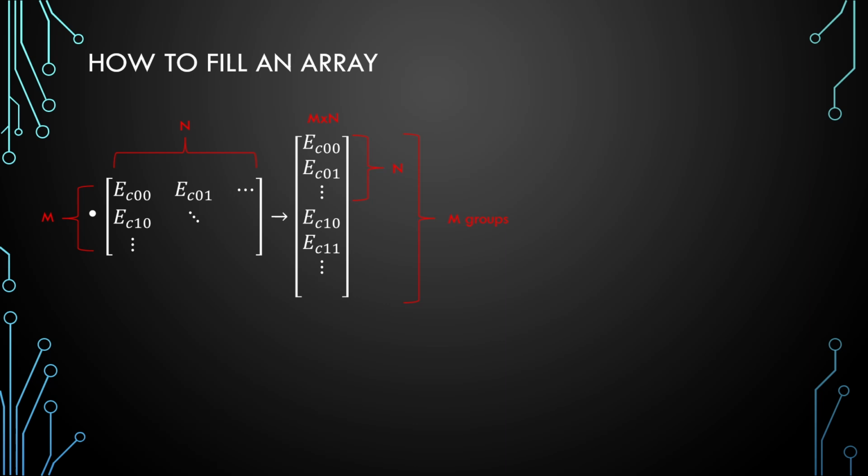Now we know how to write down our finite difference equations for both Poisson and the drift diffusion equations for 2D or even 3D problems. Then the question is, how can we solve it with codes or computer programs? As I said, it's very hard for us to deal with 3D arrays. Therefore, we need to map them to a 1D vector.